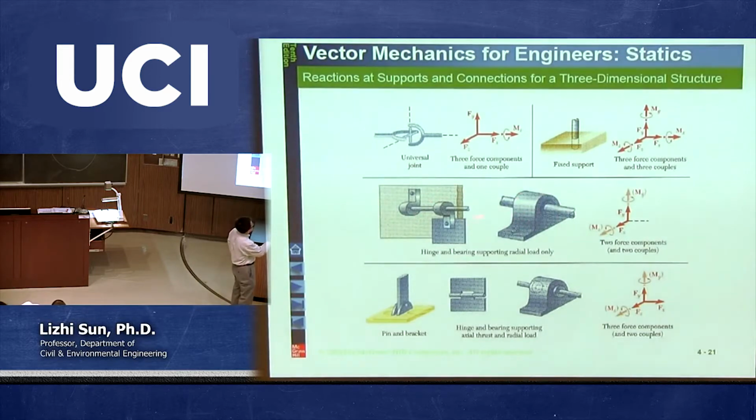These are the two, the same. So there's no resistance in this x direction, but y and z are not allowed to move. Furthermore, you can freely rotate in this x direction. It's frictionless. But it's not allowed to rotate in the y direction or z direction. So that's why these two scenarios can be described using two reaction forces and two reaction moments.